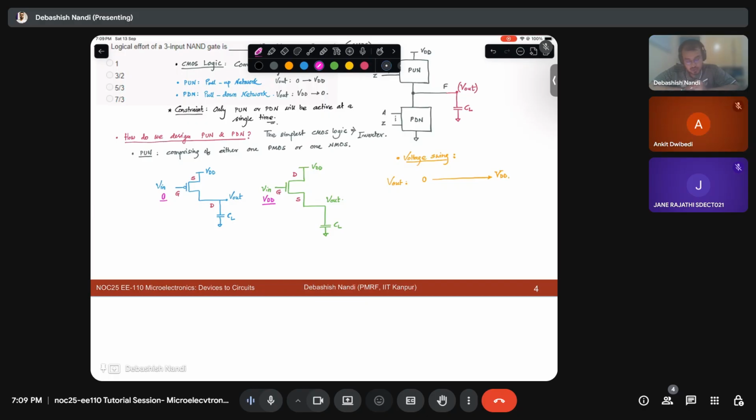So what is the condition for PMOS to be on? PMOS will be on when my VSG is greater than VTP, right? And my NMOS will be on when VGS is greater than VTN, the threshold voltage, right? Yes, sir.